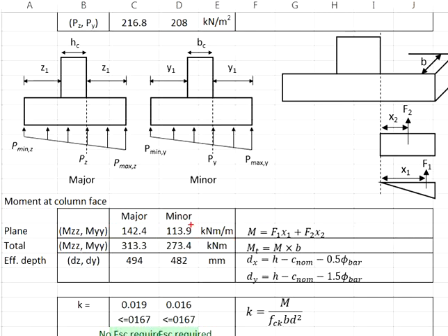The unit will be the moment per unit meter as a result of the soil pressure. This moment per meter will need to be converted into the total moment by multiplying by the width. Your total moment is equal to the moment multiplied by the width.